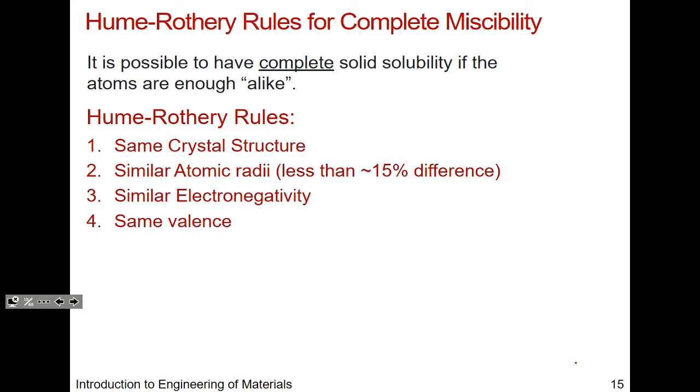So if you have magnesium oxide, magnesium's 2+, will calcium 2+ go in there? You look at the valence, so 2+ substituting for another 2+, great. That doesn't mean that if it's different valence, it won't fit. In fact, typically, if you have a higher valence, a higher oxidation state, let's say a +3 versus a +1 of the same element, the +3 is more likely to go into the same site as a +2, because it's most likely smaller than the +2, and so you can fit it in, right?